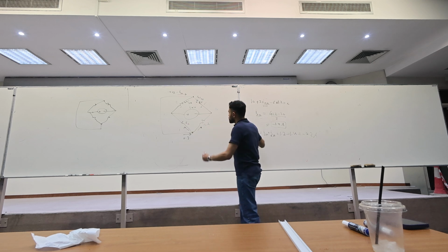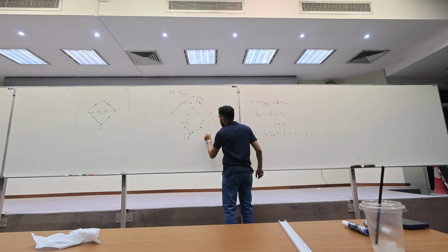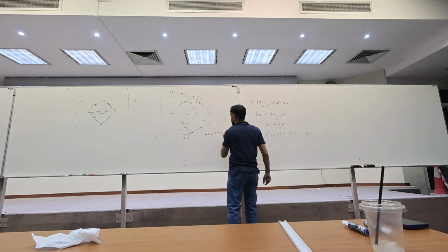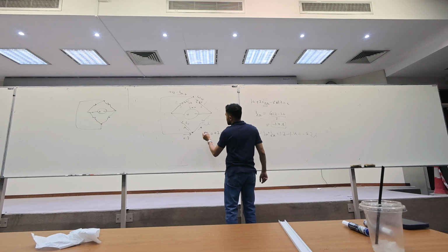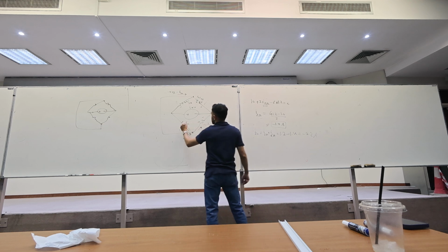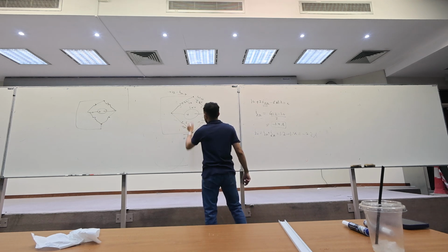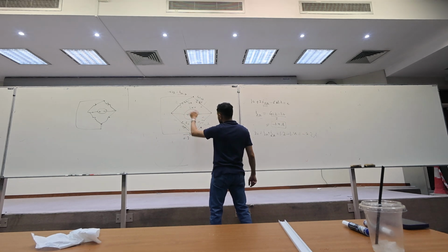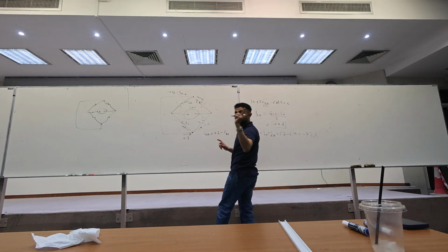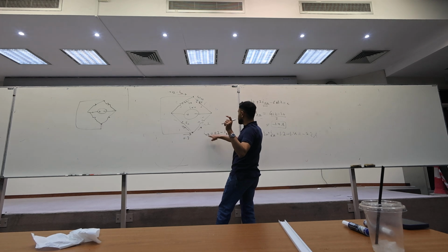So I 4 ohm is actually 0.2, which is I short circuit minus I Rx. So you can say plus, minus, and do another KVL at the lower triangle. But the key here, the trick, is you have to know that I 4 ohm is 0.2 minus IRx.